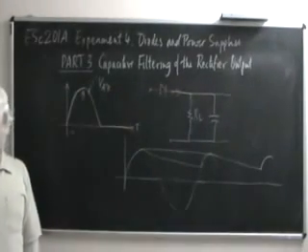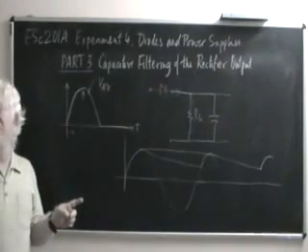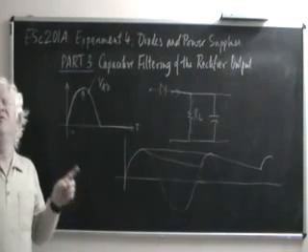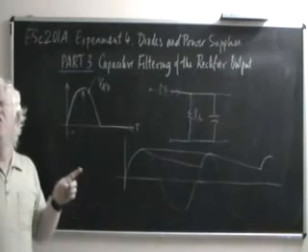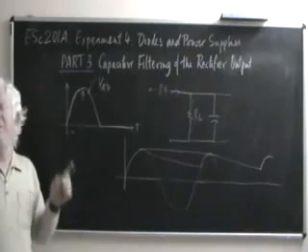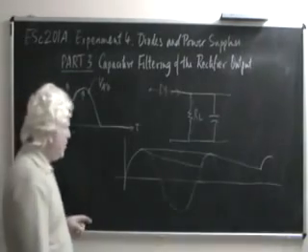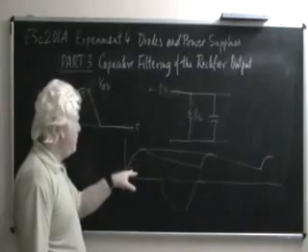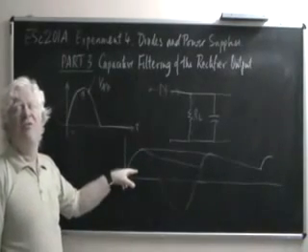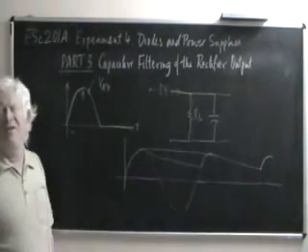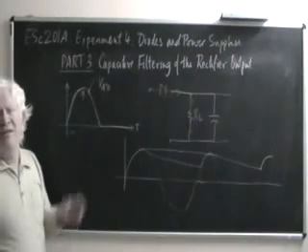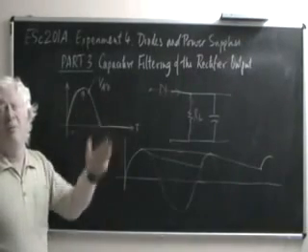So finally, with the capacitor present, unlike the case when the capacitor wasn't present, you have a voltage which is periodic and which has this sort of a shape. Let's ignore this part because we really believe this was the first cycle. In the steady state, there is no first cycle. This thing is just continuously repeating itself.